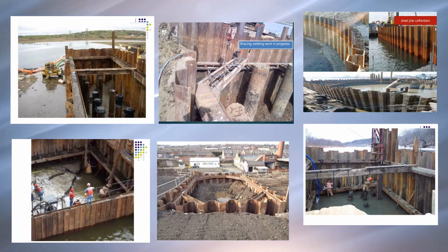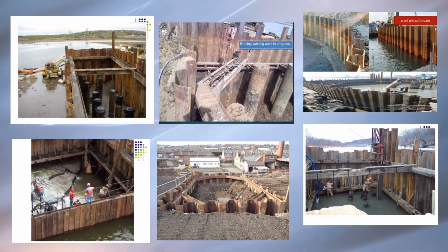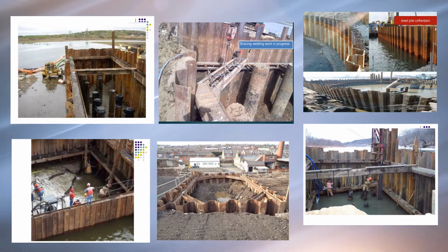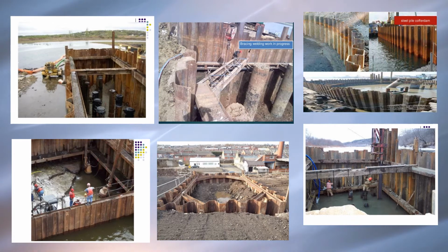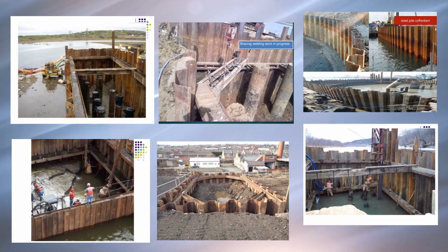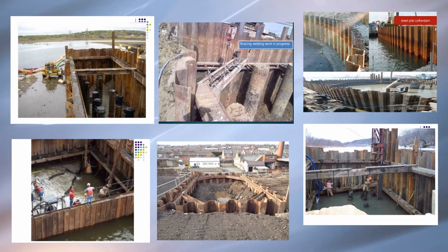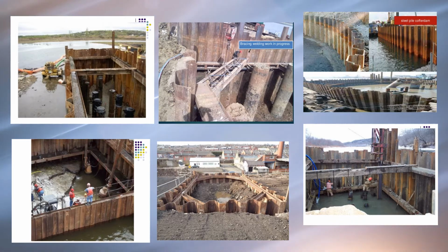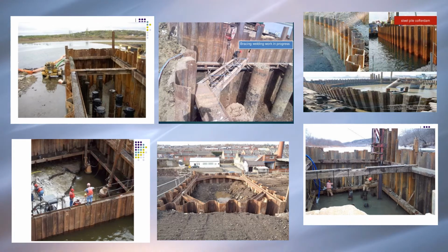Depending upon the velocity of the current of the water in the river, the center-to-center spacing of the piles may vary between 1.8 meters to 4.5 meters. Longitudinal runners called wales are then bolted to the guide piles. Steel or wooden sheet piles are then driven into the riverbed along the wales and are secured to the wales by bolts.